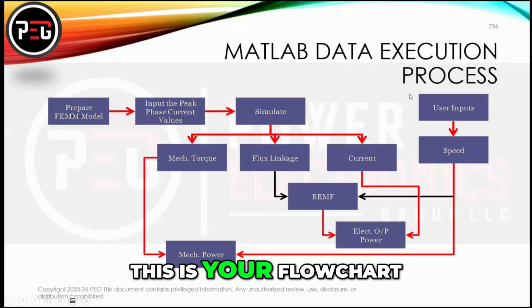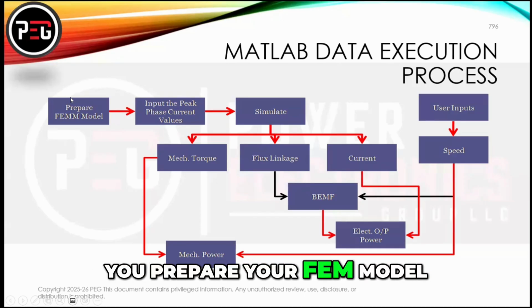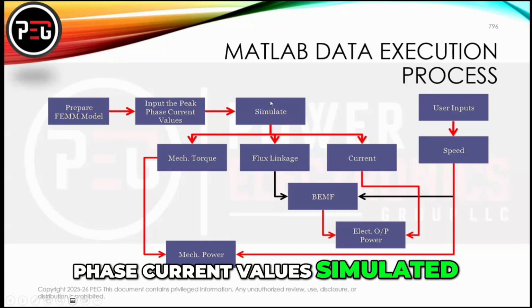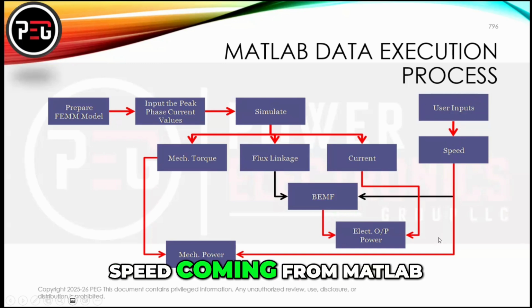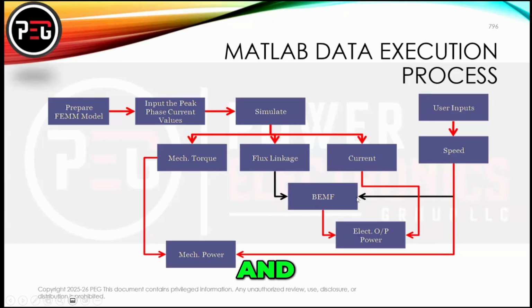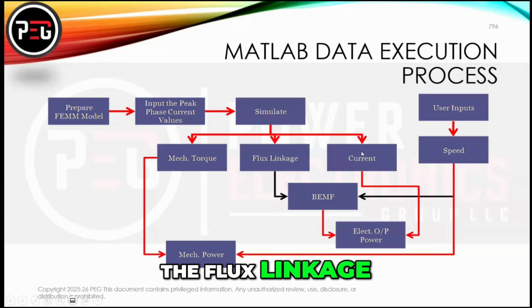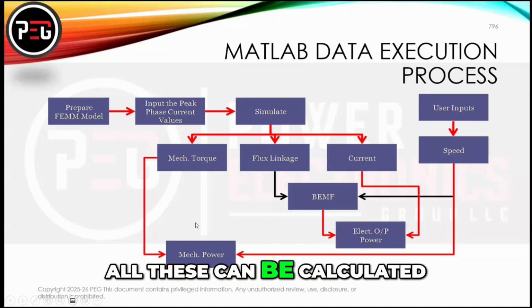So this is your flowchart for MATLAB data. You prepare your FEMM model, input the peak phase current values simulated, and then here you have user inputs of speed coming from MATLAB, and you can calculate the mechanical torque, the flux linkage, the current, electrical output power, and mechanical power. So all these can be calculated.